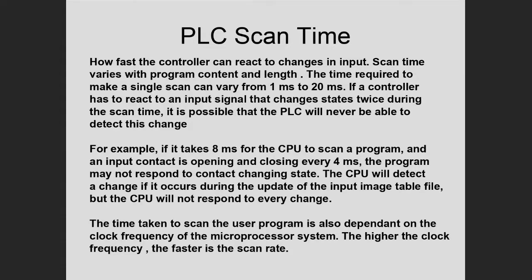Hopefully you can understand the importance of a thing called scan time. I hate to read the PowerPoint, but let me just read to emphasize certain things. How fast a controller can react to changes in the input. That's what we mean by PLC scan time. Scan time varies with program content and length. That should make sense to you.